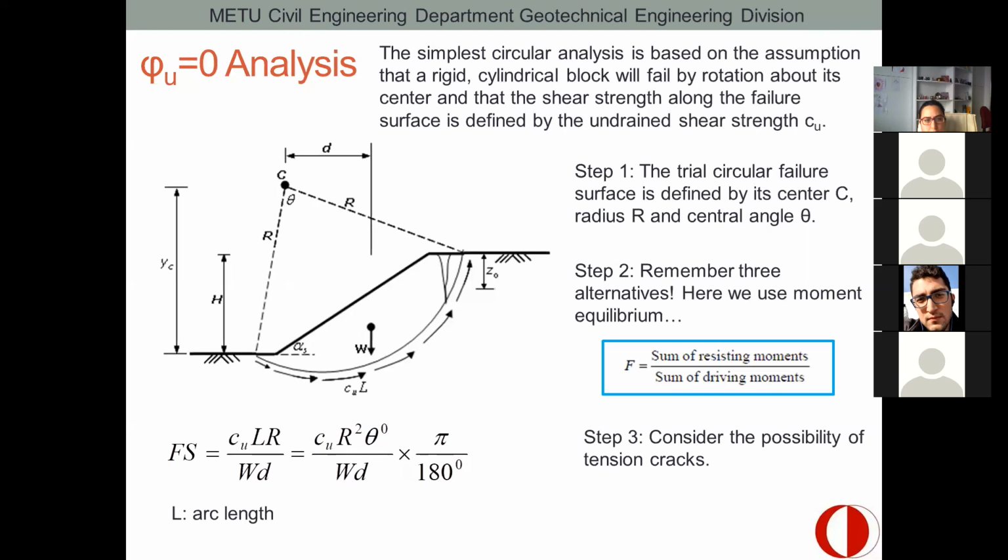Angle, which one? The alpha angle. Your friend is suggesting, hocam, if the factors of safety are too small, you can change the alpha angle. Do I reduce it or increase it? Reducing, we can reduce it. Okay. How about the h, the height of the slope? So there are typical geometrical parameters like the height of the slope and the angle of the slope that I can play with in my design, so that the factors of safety are more satisfactory in terms of performance.